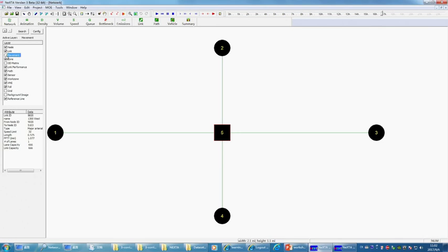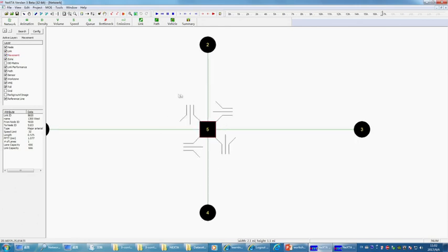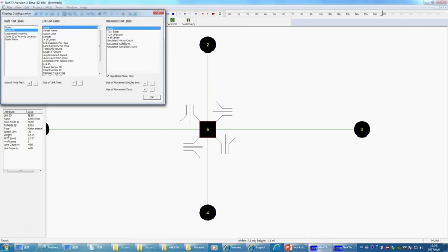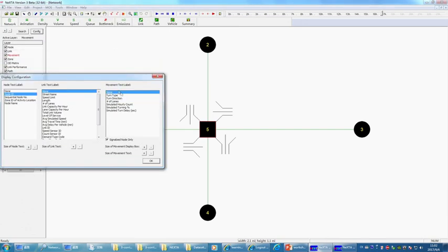If you click on the movement layer, you can see we do display the turning movements in this network setup. You can also use the configuration to display the movement, simulated link counts, simulated turning percentage, and simulated turning delay. All those are processed by the NEXTA interface. And also number of lanes, turning direction, and the turn type. Okay.